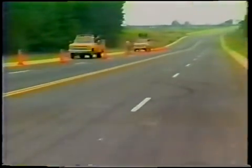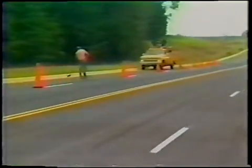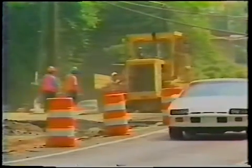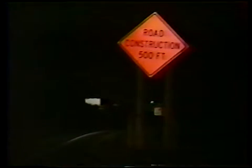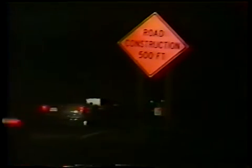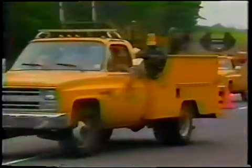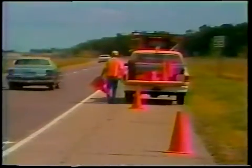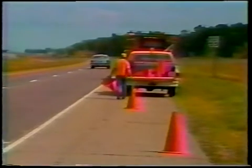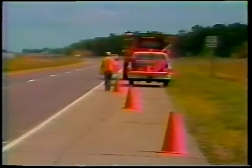Every feasible effort should be made to minimize traffic conflicts with the work area. These are suggestions. Use traffic control devices to make the travel path clearly visible to drivers. For nighttime operations, the traffic control devices must be retroreflectorized and have a large surface area. Place channelizing devices between the work area and the traveled way. Provide safe entrances and exits for work vehicles. Flags and flashing lights should be considered on work vehicles exposed to traffic, and a truck-mounted attenuator be provided whenever possible to protect work crews.